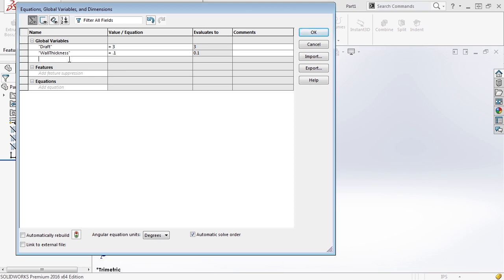Anytime they made a very thin wall outside shell to a part and realized that they couldn't make the structural ribs that same thickness, they end up getting those imperfections on the outside of the part.